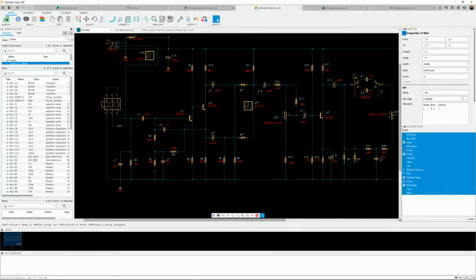The fundamental is still the guitar note, but you get a very strong second harmonic. Or is it called first harmonic? And it's without doing a tracking generator or anything. It's just basically making a distortion of your original signal. It's totally analog using rectifiers. And there's all sorts of other ways of doing this.